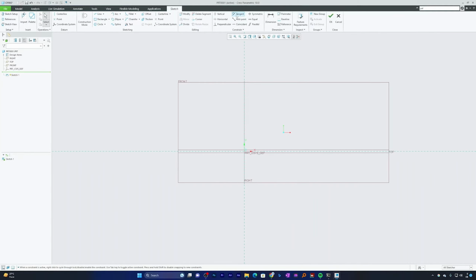Now let's talk about the normal way of applying constraints. So let me quickly draw a line here, and now I'm going to apply a horizontal constraint on this line, and there we go. Here we can see this line is now perfectly horizontal. Let's say I'm going to make this one vertical, so I can simply select the constraint, and that's how, guys, we have made this vertical. We also saw that the size of this line is too small, so I'm going to use coincident, and select the endpoint of this line segment and this reference line, making it slightly taller.